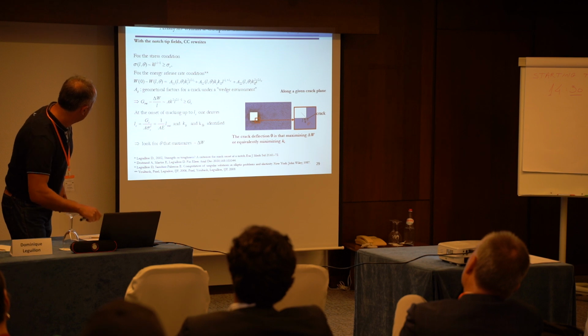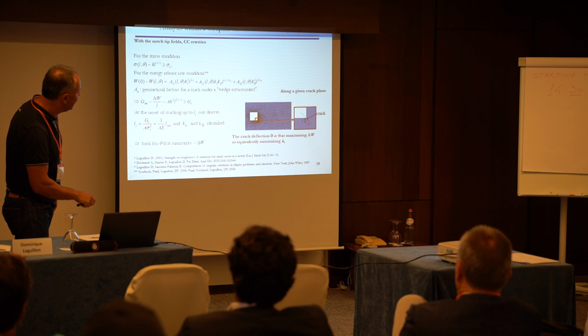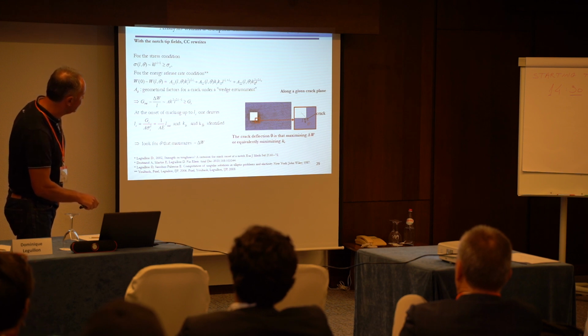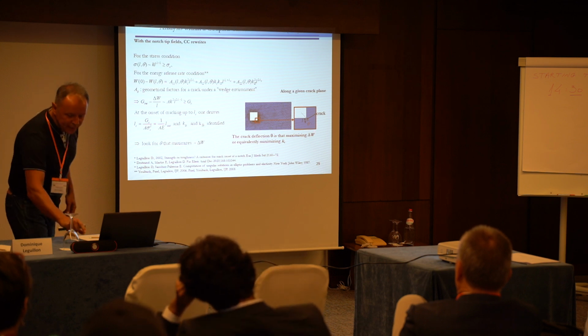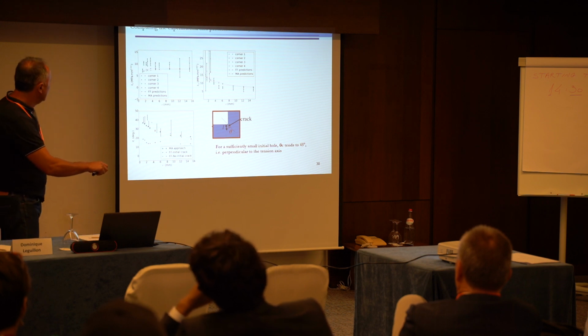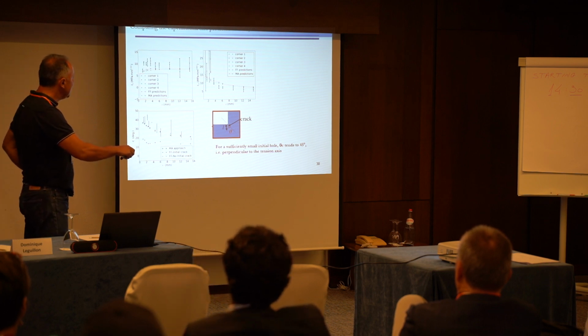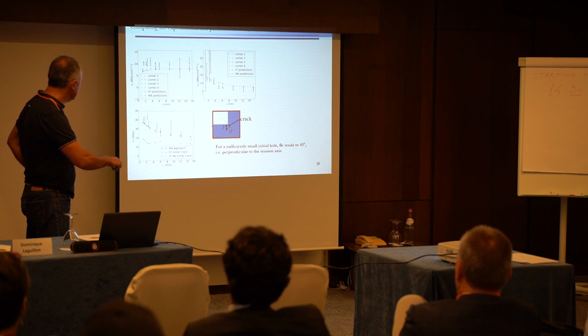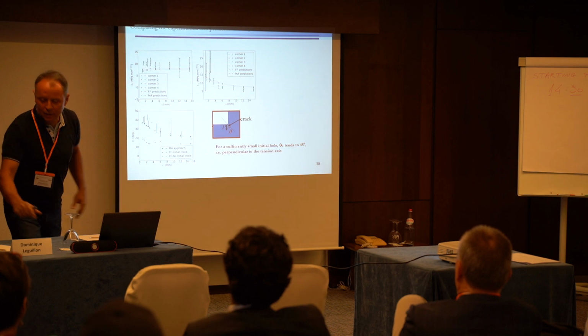So you work on that, and one condition is that the crack deflection angle theta is that which is going to maximize the energy release rate, or equivalently minimize the KC. So, doing that, you can compare the finite element calculations, the experimental work, and the matched asymptotic predictions, and the comparison is fairly acceptable.